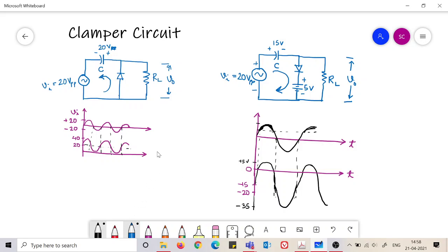Of course, why we are making these assumptions, how long they are valid, these things have to be kept in the back of your mind. In any situation, if you see that there is a very high resistance with the diode here, then of course a red flag should rise in your head, because the capacitor would not get charged instantaneously. If you see a very low resistance here, then the capacitor will get discharged very rapidly.